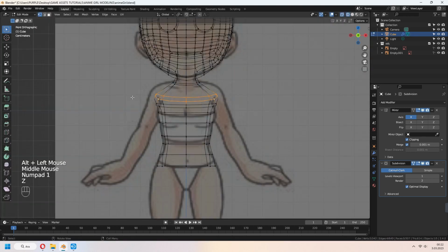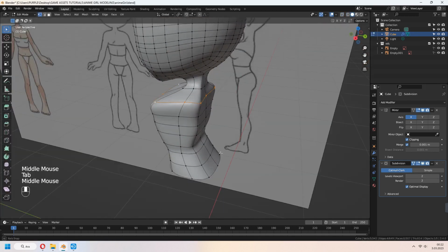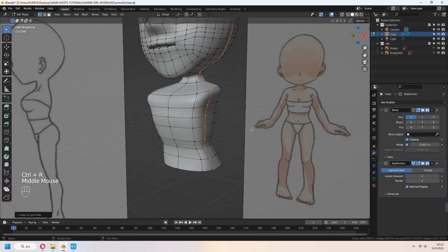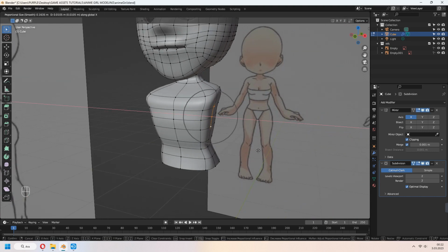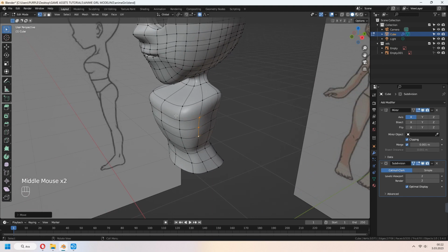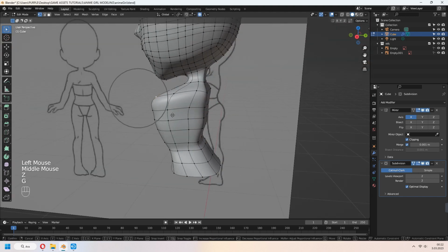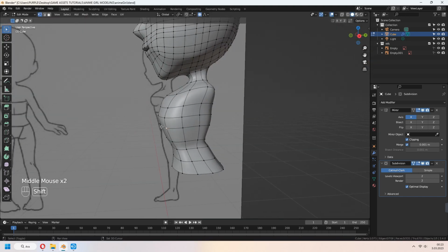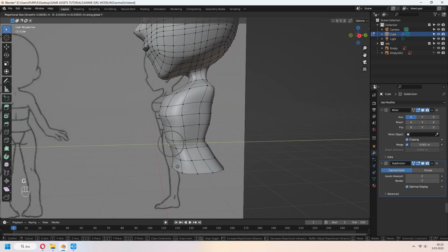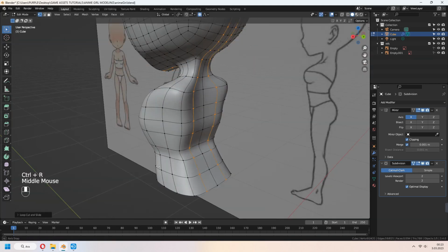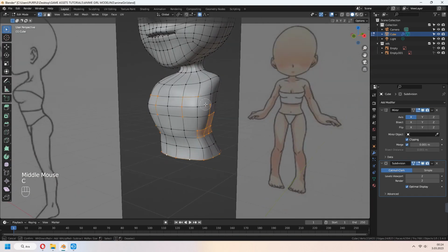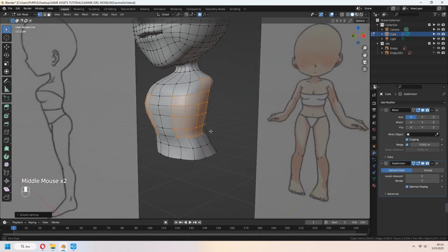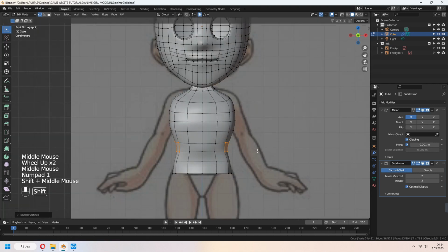It will be a bit flat look in solid view. You can smooth your vertices or add another loop cut with Ctrl R and G to move these vertices with proportional edit. Our torso is ready now.